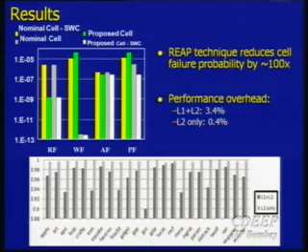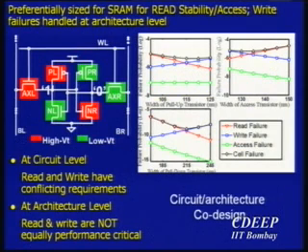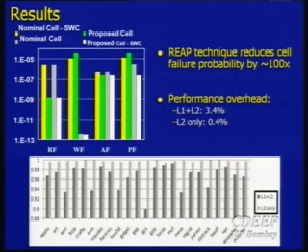VTs, basically I haven't changed my VT, I've only sized it. No, the green and the red are only for process variations. So basically W has been changed. W would change leakage, but it just changes leakage linearly.